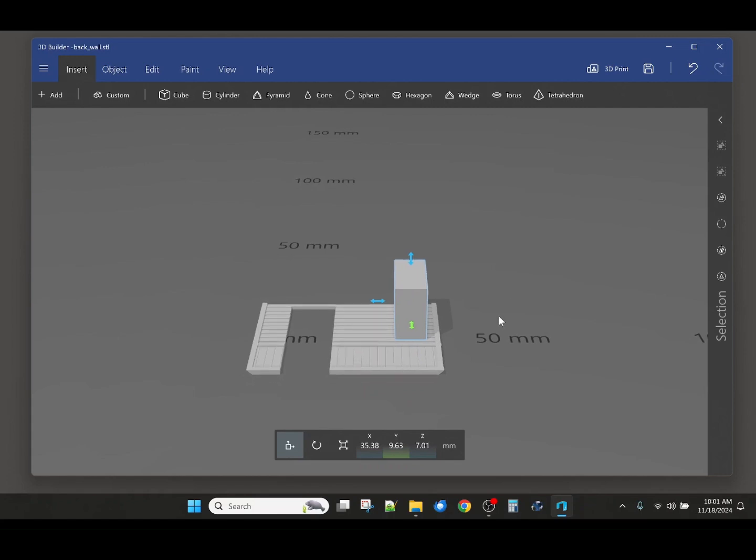Now position the opening centered between the wall right-hand corner and the door edge, and put the bottom right on the top of the clapboard wainscoting trim board.